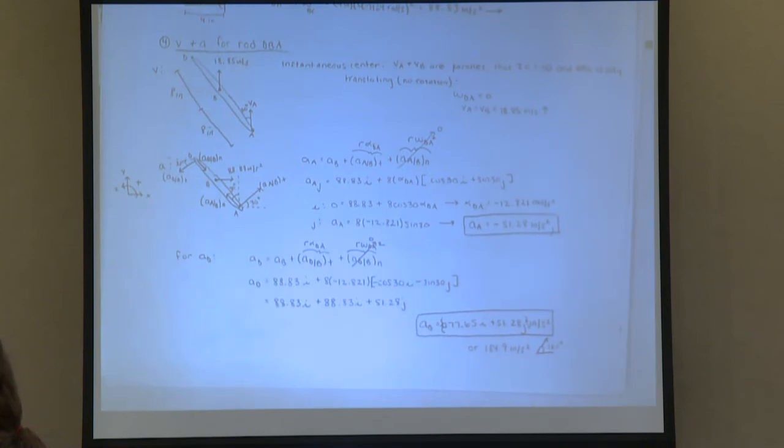It's not too bad. These are just tedious. My suggestion for these problems is to start with the one that you know the most about. Generally the problem will say this one has an angular velocity of blank, and it's constant. Solve for this point here. So you start with the one that you're given, find the point, then go to the next one.